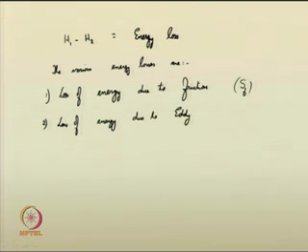As these are non-prismatic channels, there will be considerable eddy currents also. So, those things also cause loss in energy. I can give the loss of energy due to friction as HF and the loss due to eddy currents as HE.